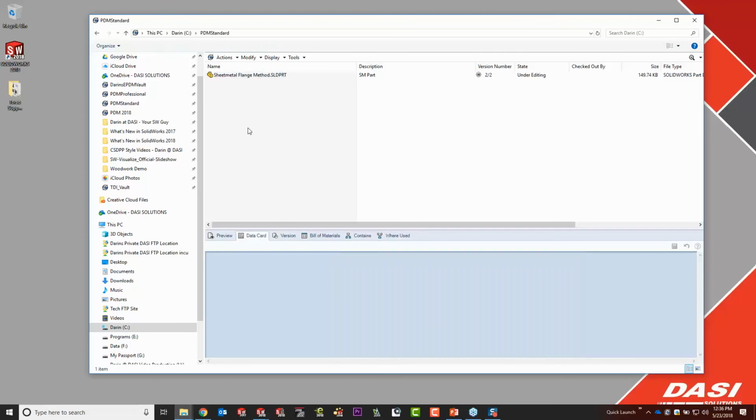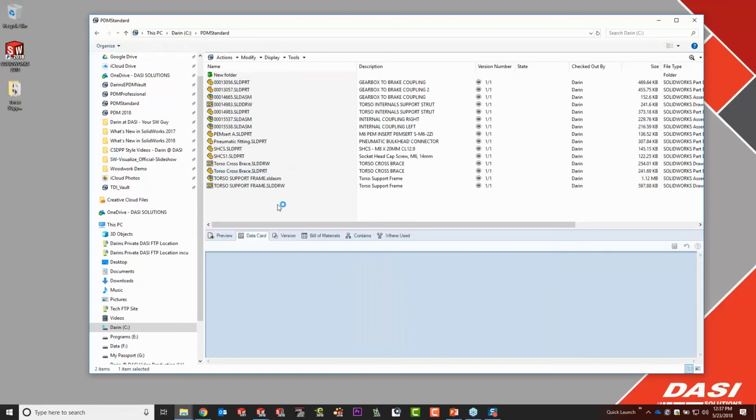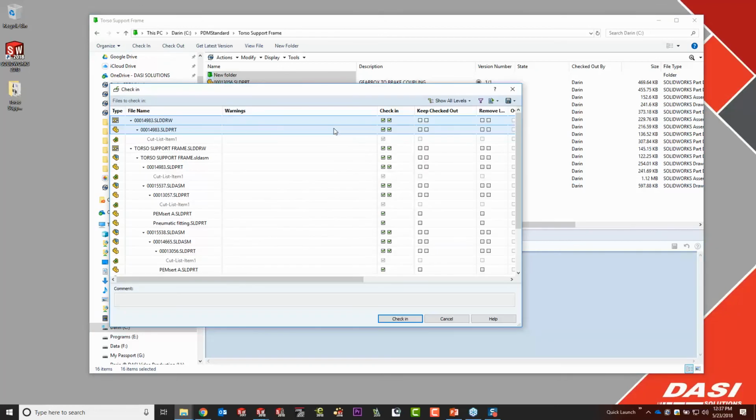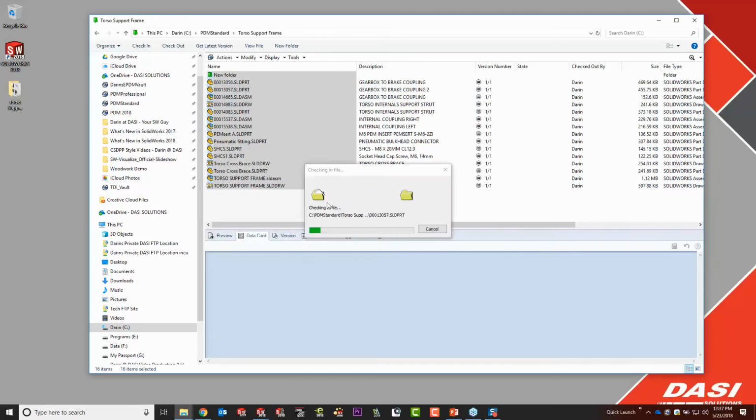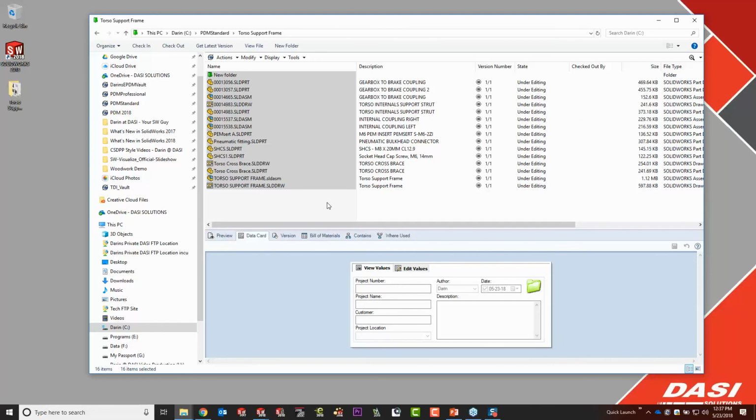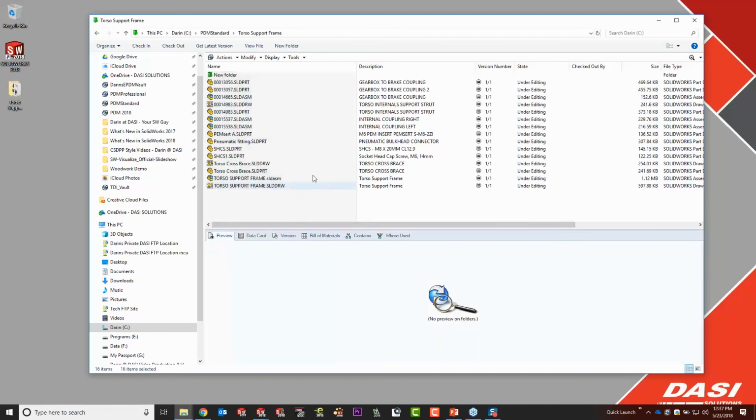Now for existing data, which many of our customers obviously have, this is still just a Windows folder through and through. So when I right click and simply copy a folder into the Vault, that's how I can populate existing data. Now the data goes into the Vault initially in my local Vault view because I'm the person performing this operation. So a simple operation of grabbing the files and hitting check-in is now going to put these files in the central Vault and allow other valid or permission-based users to be able to do what their permissions allow with these documents.